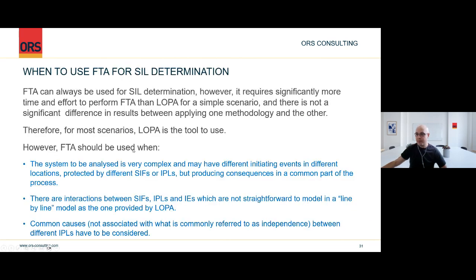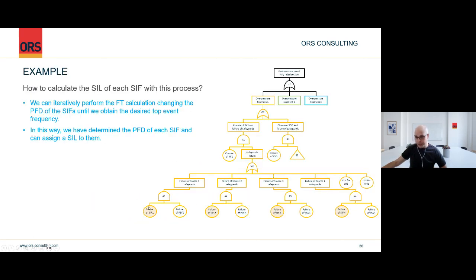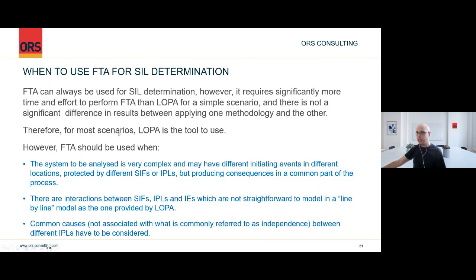And yeah, that is the way that you would use fault tree to calculate the required SIL for a lot of safety instrumented functions that are working in one system at the same time to prevent against a single hazardous event.